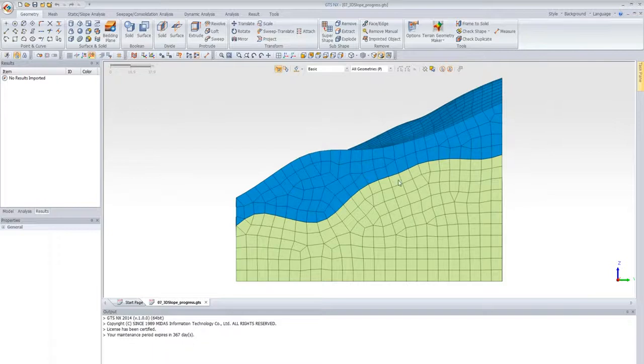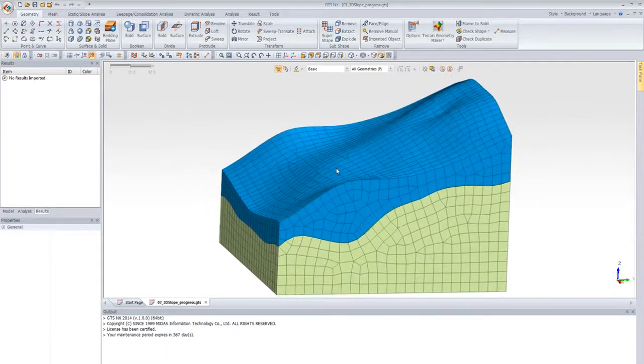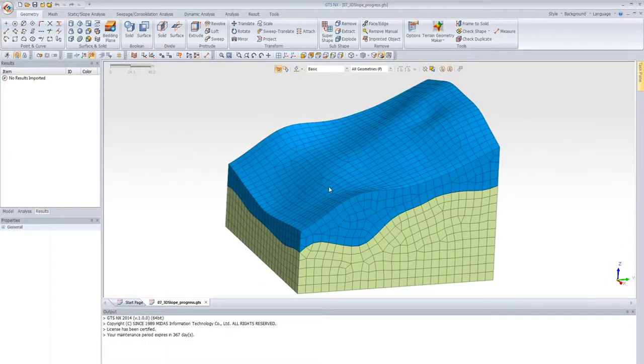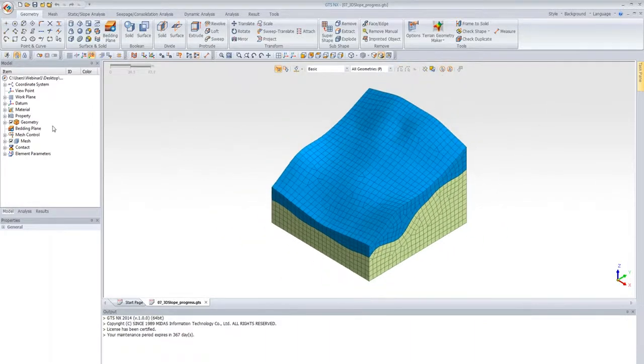As you can see, the way the contours change, the slope could be very different for each one of these. Maybe if you take a certain series of cuts along the length of the slope here, the factor of safety, or the forces acting on them, could be very different. So just using the 3D modeling aspect here, you can create contours that are very in-depth, very detailed. For example, if I wanted to create a detailed 3D contour such as this, it's actually quite simple if you have a spreadsheet representing all of your values. So let's say I want to create a detailed 3D contour for the strata as well as the surface. So let's go back here, and let's turn the geometry off for now.